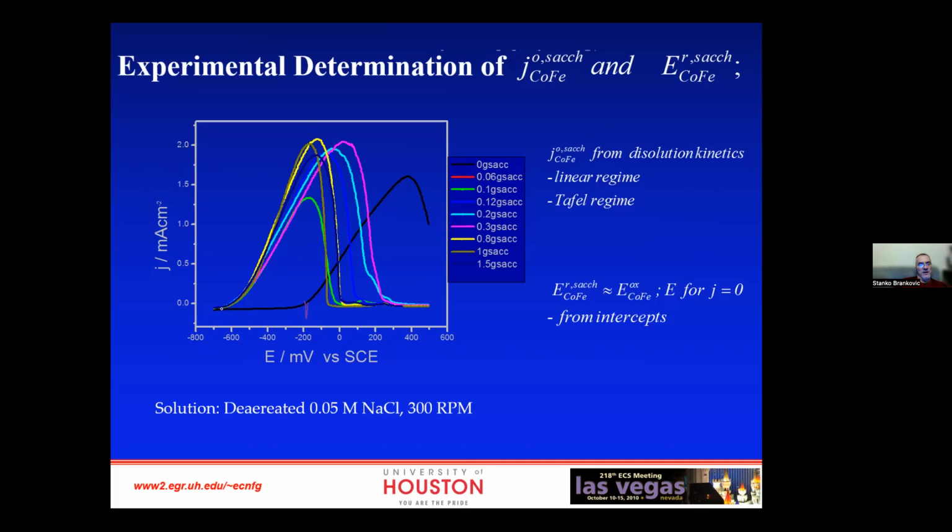While most of the alloys that actually are deposited with saccharin in the solution, when you try to dissolve them, they start dissolution pretty much all at the same time. Now the dissolution peaks, obviously, here, are not all at the same position, but dissolution starts about at the same potential. All right.